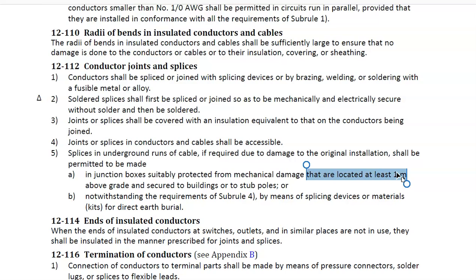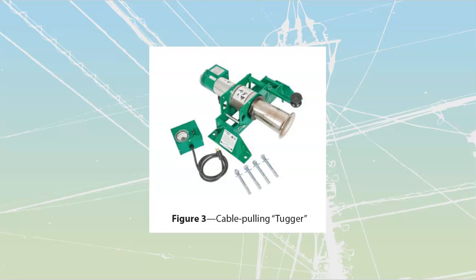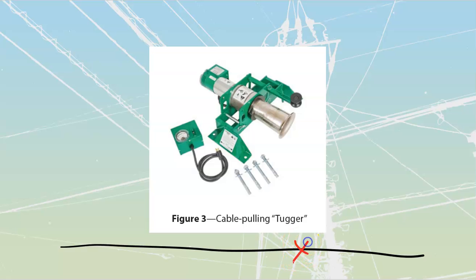You know, bring it up, splice it, and then allow that thing to go underground. Obviously, if you're going to do the stub pole, you are going to lose some conductor length. So if I've got a cable that's going underground like that, and then somebody digs into it like that, there's a chance that you might have enough length still over there that you can splice those together end to end, if you expose a bit of cable and you can straighten that thing out. But usually what you're going to end up having to do is take out a whole section, a chunk like this, push some up and some.